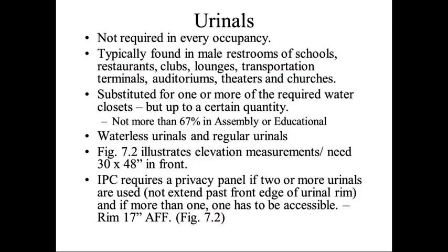Urinals. They're not required in every occupancy type or classification. They're typically found in male restrooms of schools, restaurants, clubs, lounges, transportation terminals, auditoriums, theaters, and churches. They can substitute for one or more of the required water closets, but up to a certain quantity. Not more than 67% in assembly or education can be urinals.